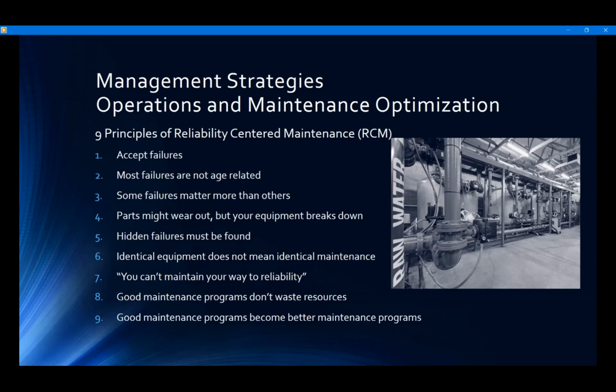This is an interesting concept to dig into. Hidden failures are typically failures of one or more components aligned in parallel with no indication of failure for each individual component. For example, one of 2 components could fail, but since each one by itself can satisfy the function, only when the second one fails will the functional failure become evident. Therefore, the failure of the first component is potentially critical. These must be identified.